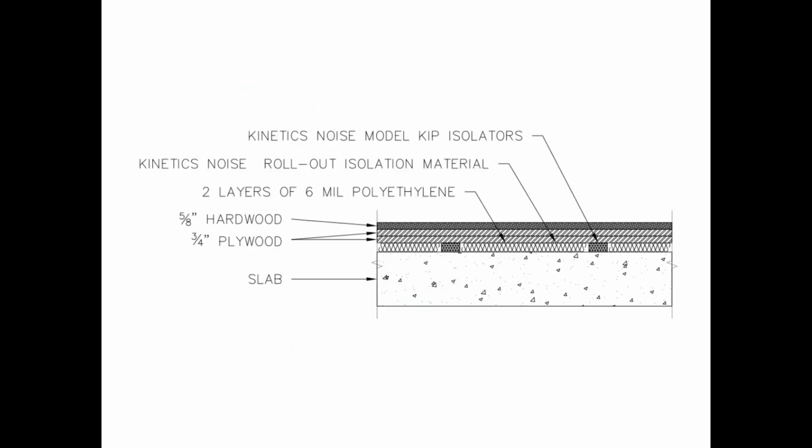This is how we isolated the floor in this case. You have these neoprene blocks and you have some fiberglass insulation that rolls out in between them. And a couple layers of plywood, kind of like a subfloor, and then add hardwood floors. Often it's good to have hardwood floors, and then you can roll out a thick rug with a pad underneath it. Maybe you can, if you just want to put them under the drum set or the things that are under the amps, the things that are noisier, it gives you flexibility instead of just carpeting everything to begin with.